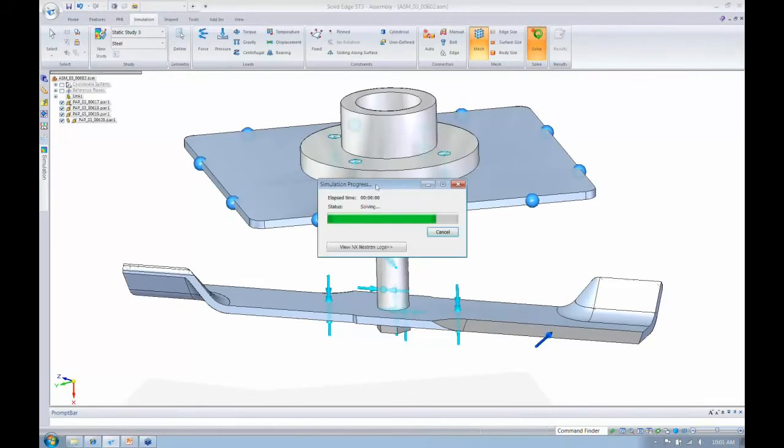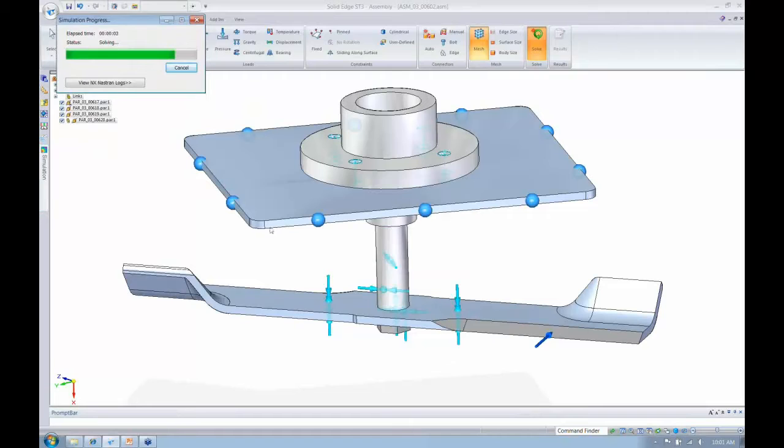I'm going to click Solve here, and while this is solving, in most situations you're going to want to capture the bending through your parts. So you're going to use the solid or the surface element. The reason for that is because if you imagine I'm going to put 2 or 3 elements through here, they're going to have to be very tiny, and they're going to cause all these other elements to be very tiny, which is going to drive up my solve time. A surface element is, like I said, represented by 2D geometry at the midplane here. It actually has translational and rotational degrees of freedom. So it has the motion in the X, Y, and Z, but it also has rotation about the X, rotation about the Y, and rotation about the Z.